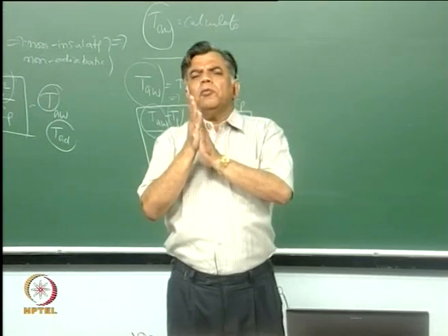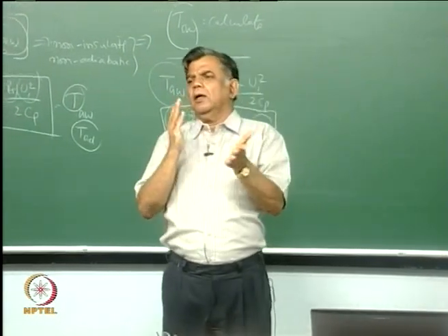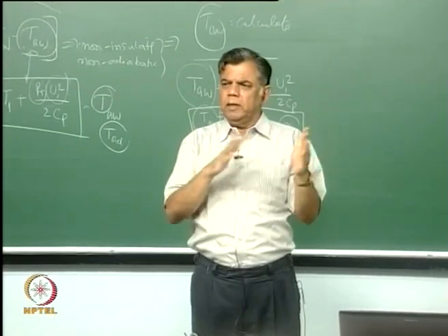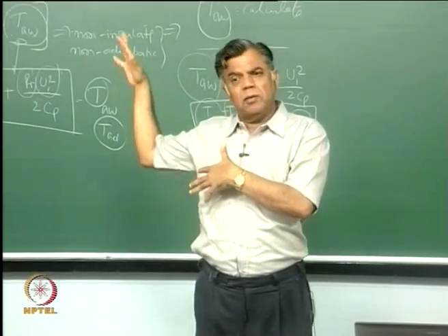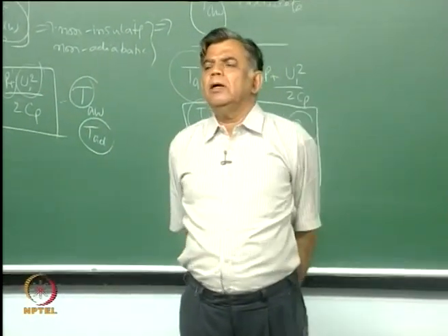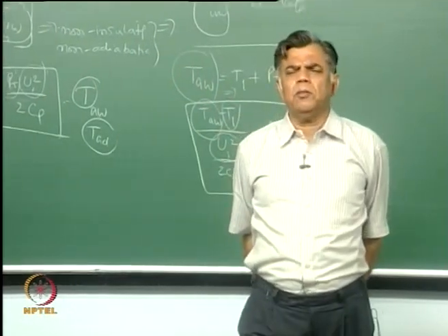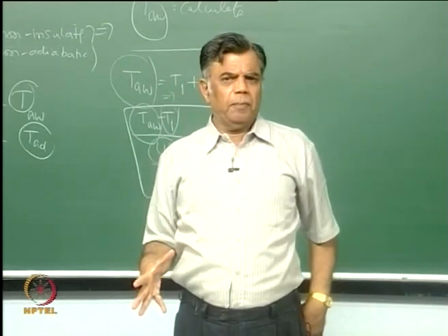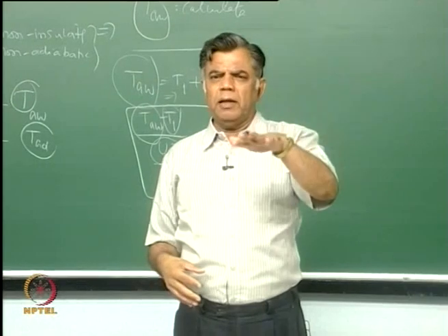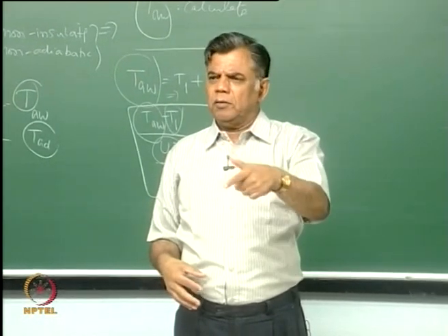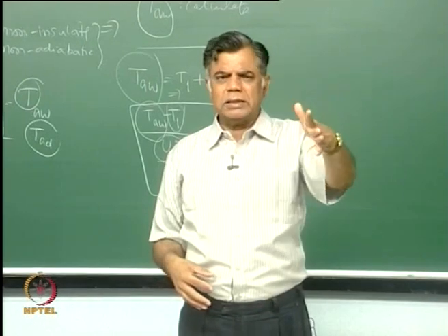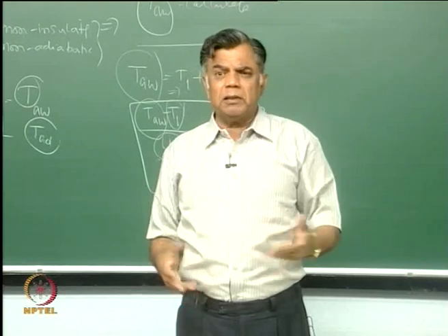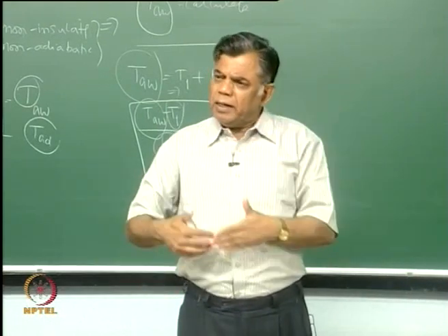So we do this Couette flow generally in the beginning of the laminar flows. We never said laminar, we did not say turbulent, because it is all for laminar. We wrote the expressions for laminar. We do this, therefore, to first of all understand the procedure of solution of a convective heat transfer problem, starting from the physical model. I say this very often, you have to start with the physical model, ad nauseam as I say, physical model, mathematical model, simplification of the equations if they are very complex, and neither equations are complex. Then take the simplified version.